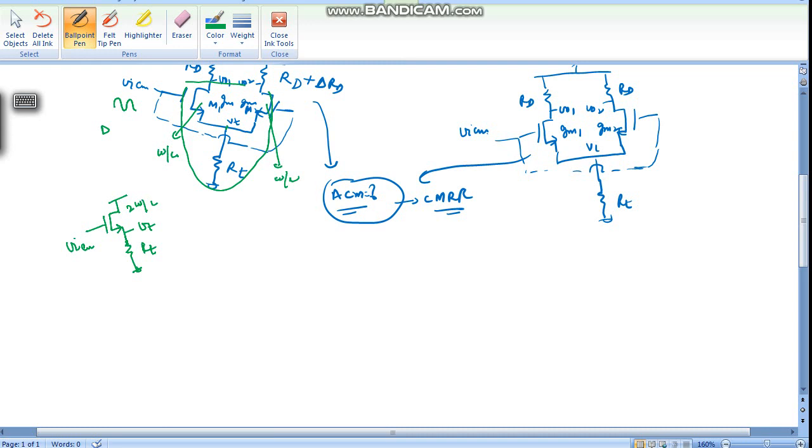So what we are going to do is see how much Vt is going to vary. So I tail is whatever Vt is varying divided by Rt. Now both devices are symmetric, M1 M2, so ID1 equals ID2 equals I tail divided by 2.